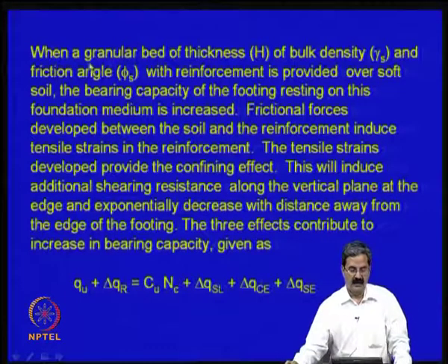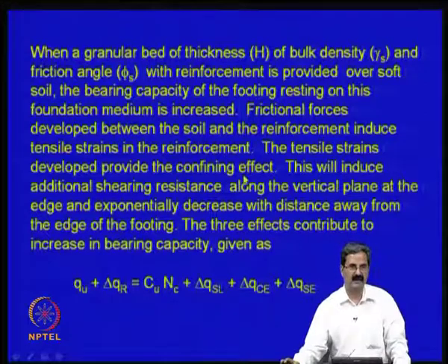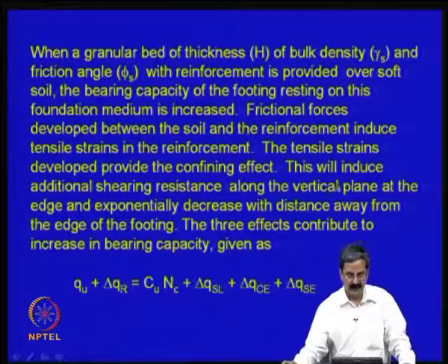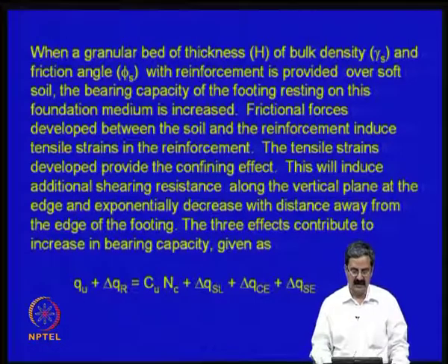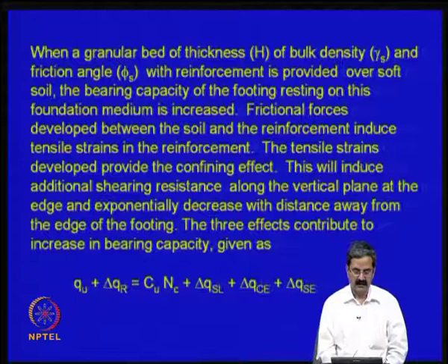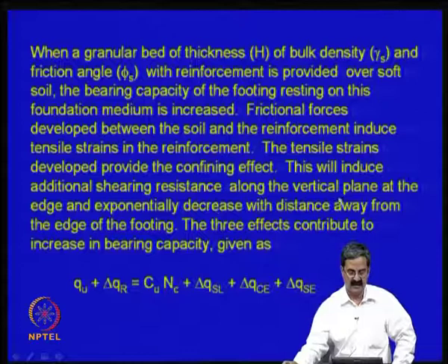So, when a granular bed of thickness h, bulk density gamma s and friction angle phi s is used with reinforcement, the bearing capacity is increased. The frictional forces developed between the soil and reinforcement induce tensile strains, and the tensile strains developed provide a confinement effect. This will also induce additional shearing resistance along the vertical plane at the edge, because at the edges it is creating additional shearing resistance, which increases exponentially with the distance away from the edge of the footing.